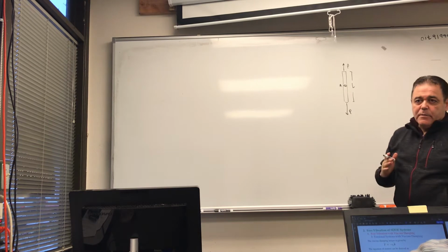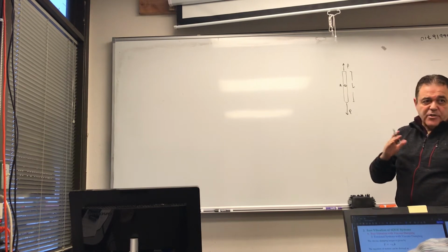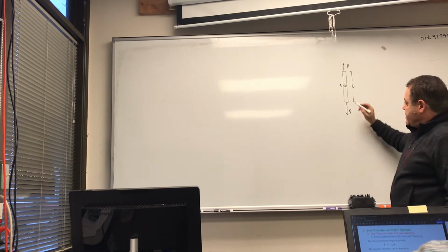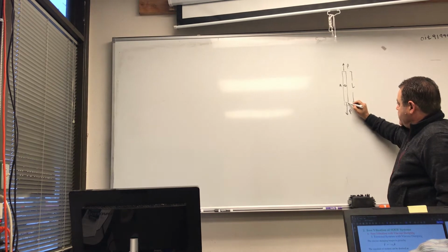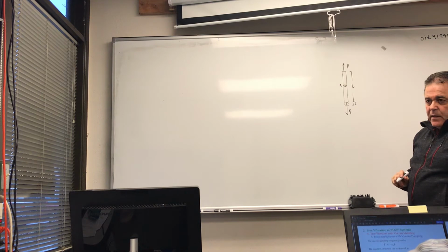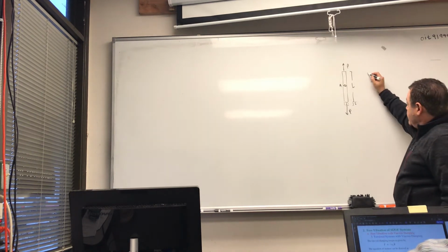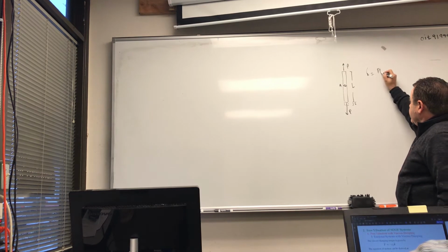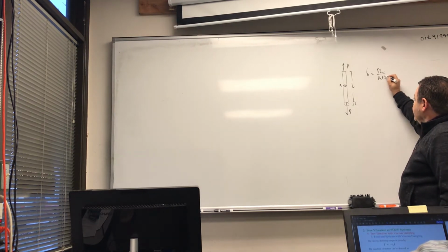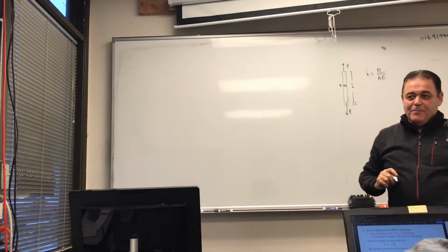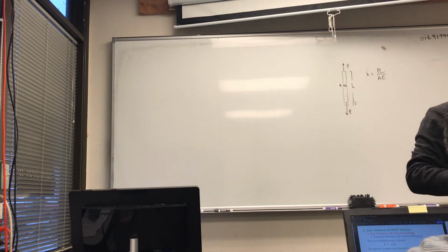What's going to happen to the bar in the elastic range? It will elongate, or extend, by an amount which I call delta. What is delta a function of? Delta equals PL over A... PL over AE, exactly.